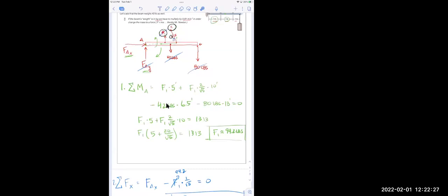But a minute ago, we just discovered this was 94 pounds all by itself, and this was also 94 pounds. So these two are having to pull up so hard to keep this thing from rotating that they outpulled the 122 from this, and therefore this is actually backwards. It's actually going the other direction. Does it make sense? You would need to know that in terms of how it was attached to the wall. Maybe it makes a difference that that pull is up or down.